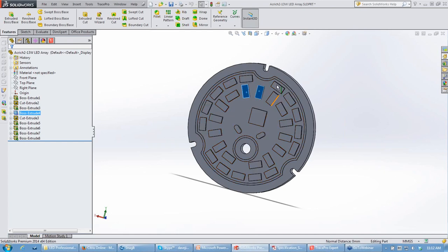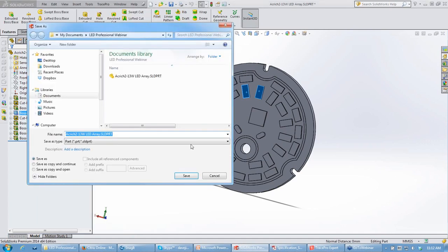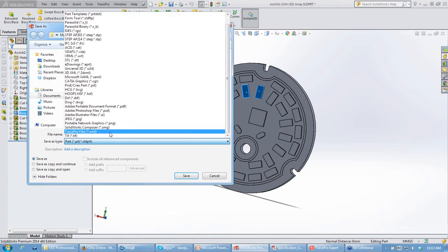And I'm going to set up my wavelengths. I'm going to use a feature called Calculated Wavelengths. And I'm going to go from 0.4 microns, 400 nanometers, to 0.75 microns, 750 nanometers. And I'm going to use, in this dialog where it says number sign include, 10 wavelengths.